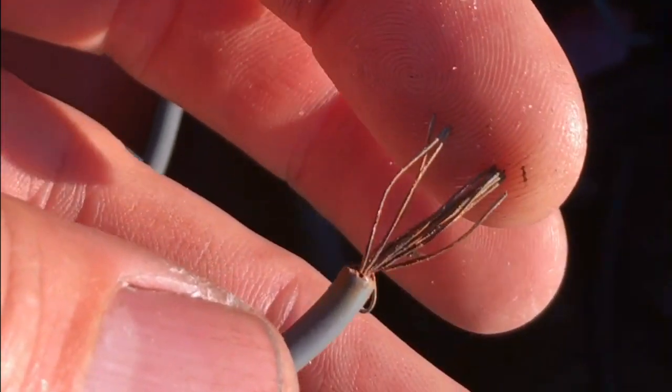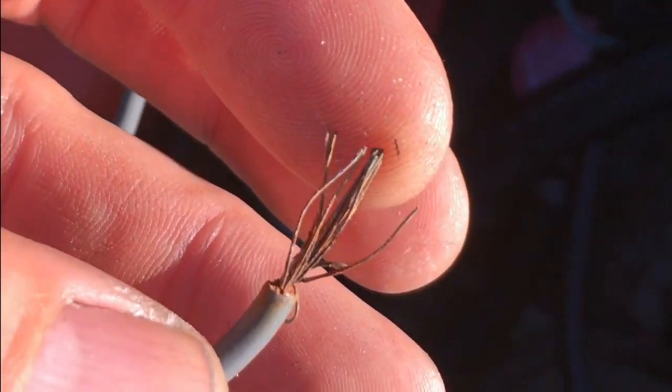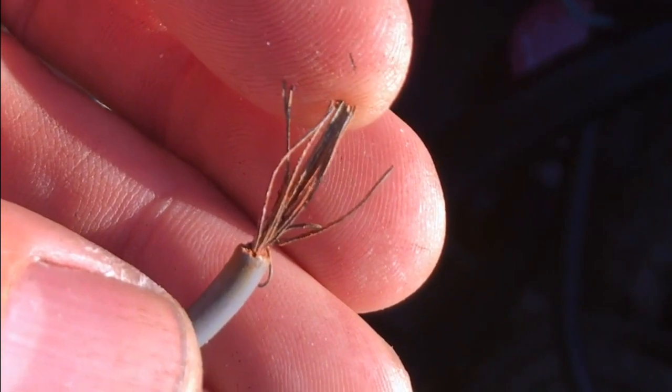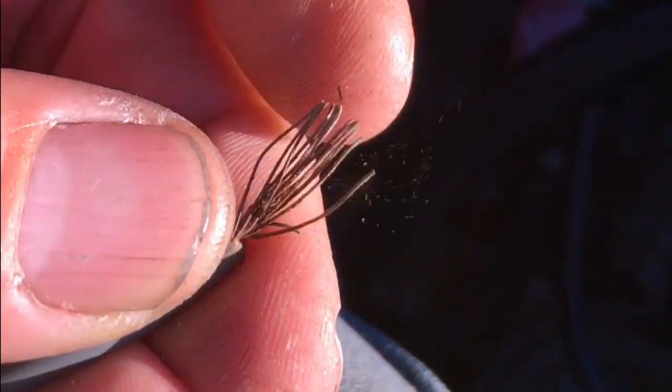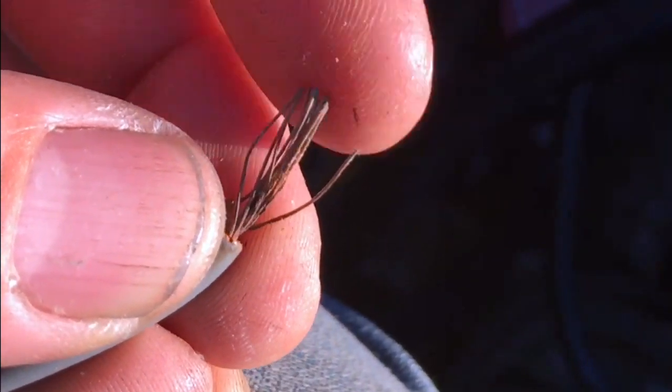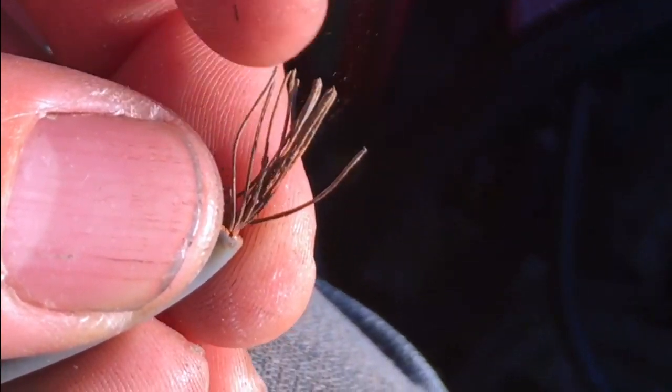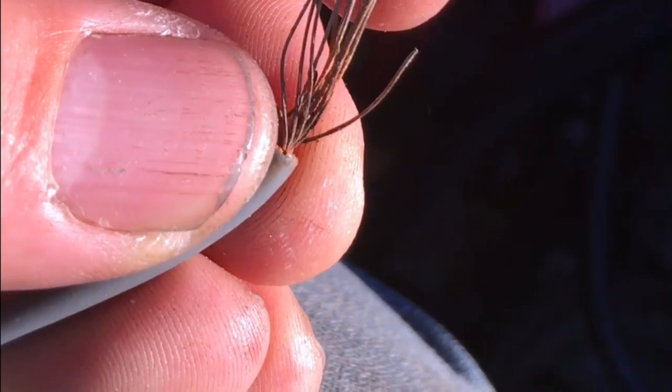This is the sort of thing I'm talking about, where there's never any shortage of this surface corrosion on boats. So wherever there's boats and wiring, unless it's really done well and really sealed well, you're going to end up with this sort of corrosion, which will definitely add resistance into the circuit and cause a voltage drop. Okay, well let's head back to the workshop and get started.